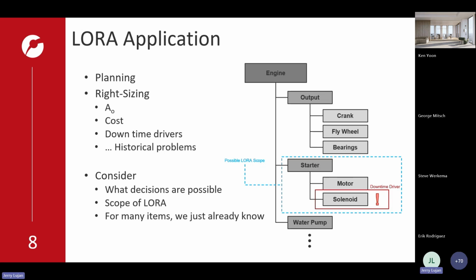Well, they get a transmission, they open it up, they're going to take out the plates, they're going to inspect the plates. Any plates that are worn down, they're going to throw away, they're going to put new ones in. They're going to look at the valve bodies, they're going to take out the valve bodies, they're going to look for broken seals and replace the seals. The depot is doing the exact same thing that the organizational unit is doing, it's just doing it on a subsystem. Right? Unless they're bending metal or resoldering, and there are true repairs out there, don't get me wrong, but they are doing the same thing that the organizational unit is doing, just on a subsystem.